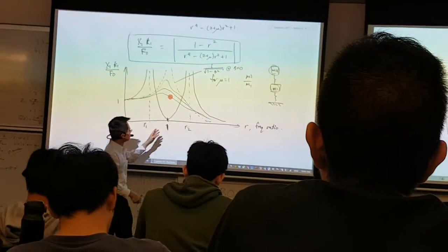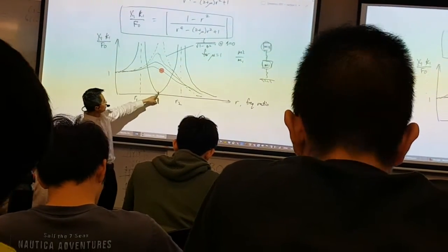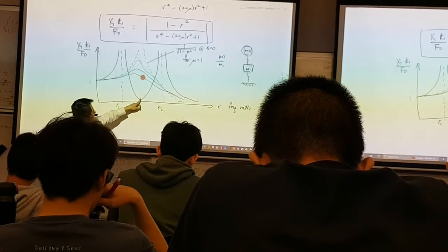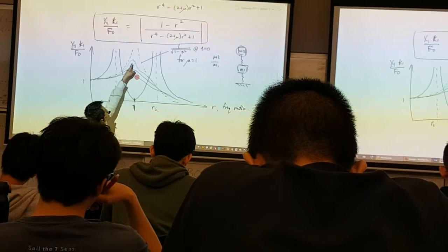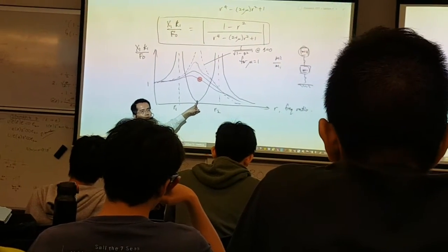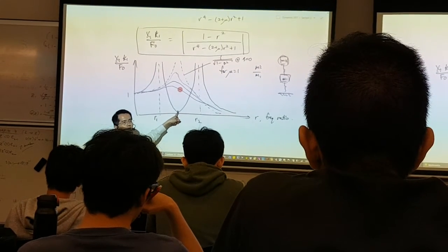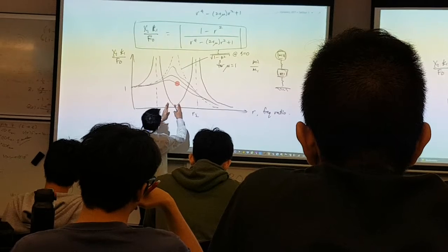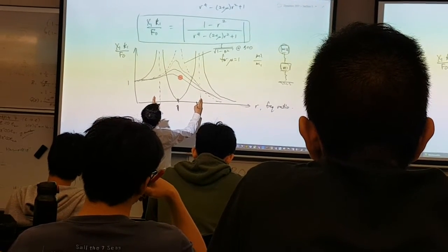So what that means in this graph is that it used to be resonating at this point over here. But I would still want that operating frequency. What I can do is convert it into a 2 degree of freedom system, and hence that resonance frequency was split up in that way.